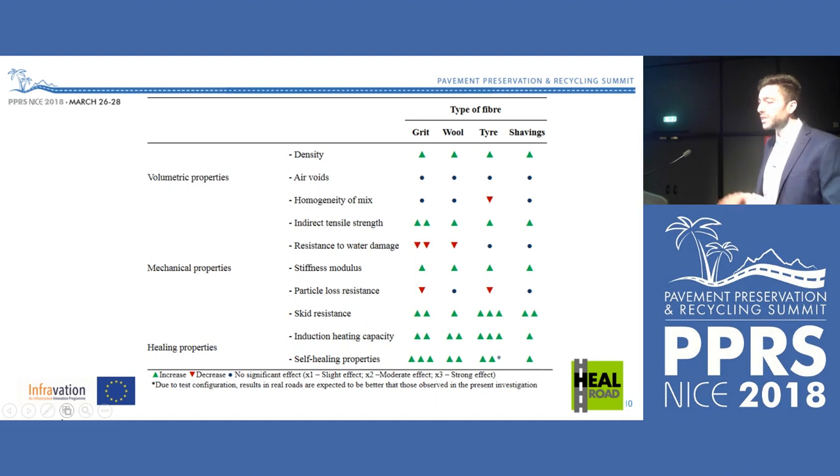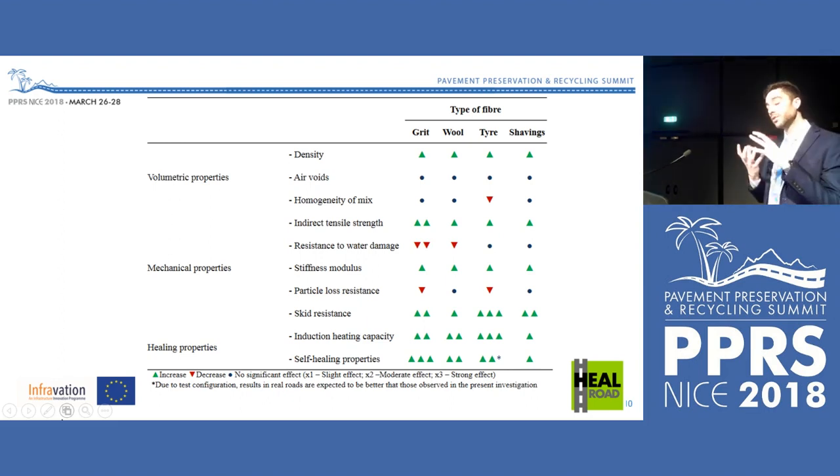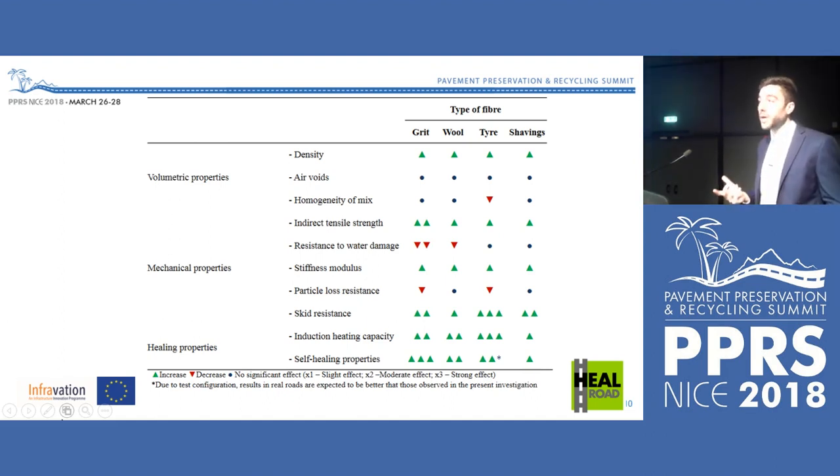water. A similar thing happened with the tire fibers, because what they presented is a really, really good capacity for heating. They heat really well. So we can use them actually far from the coil, so in bottom layers, and they're going to heat very well. At the same time, we have found that when we use this type of tire fibers in the surface, they tend to leave some emerging spikes from the surface that could compromise the safety of our road users.